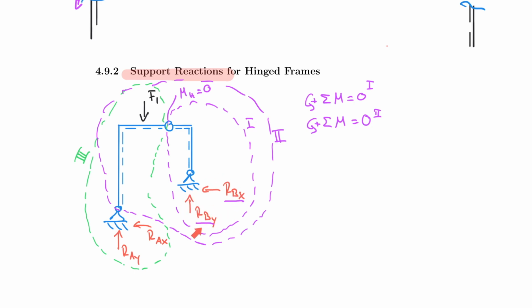So like I said, a very common mistake is that students try to set up this cut 1 and then this cut 2 and then they want to solve it. But what those students did not account for is that then they end up with two equations with four unknowns, and that's unsolvable. Alternatively, however, you could set up a second equation that goes along with this cut here.